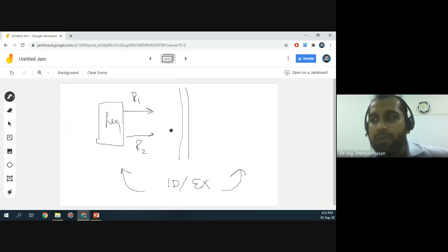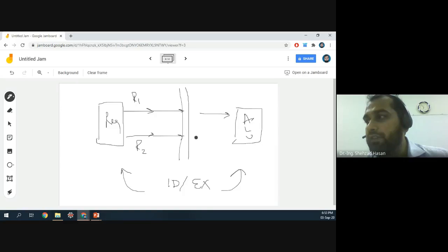So this is the normal procedure: the two register contents go to the pipeline register ID/EX, and in the next stage we have an ALU which is going to use these registers, and then it's going to generate a signal whether they both are equal or not.